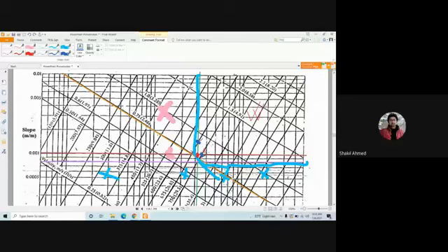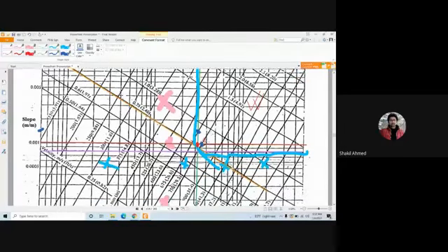but there is a but. Look at this. Although at this point your diameter is small relative to that one, what is your slope requirement here, guys? Around 0.0015. But for this point, although the diameter is higher, the slope is 0.001. That means here your pipe cost will be smaller but the earthwork excavation cost will be higher. And at this point, although your pipe cost will be higher, the earthwork excavation cost will be smaller because the slope is 0.001 here. Am I right? Yes, sir.